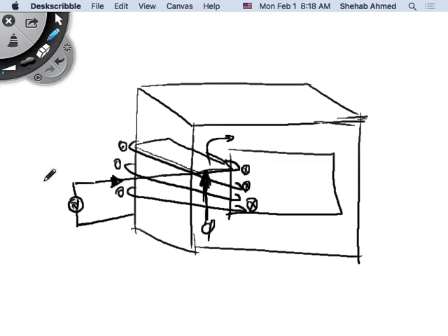Okay, so what you do is, of course, if you have a big cross-sectional area for the current to flow, then you have big loops of current flowing in this area, and the result is, if this is an electrically conducting material, that will also have losses, right? So these will be eddy currents that will create some losses in the system, in the transformer. So you want to make sure that as the flux crosses, it sees smaller areas, right? So it creates less losses.